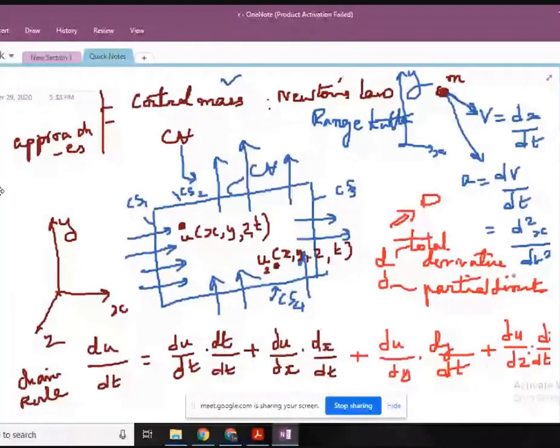You provide energy in the form of a flame which heats up the fluid, and the fluid is kept open in ambient conditions. You know that the boiling temperature, at which the bubbles form, depends on the ambient pressure as well as the temperature rise you give. So two parameters immediately come to mind which can affect the boiling point: the heat you have provided in terms of delta T, and the ambient pressure you have set around the fluid.